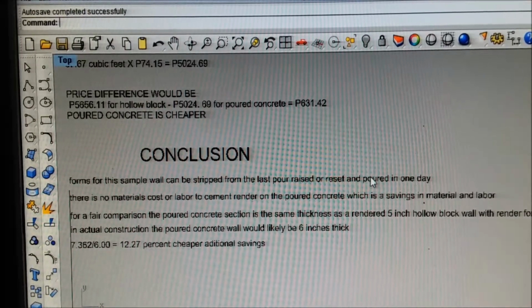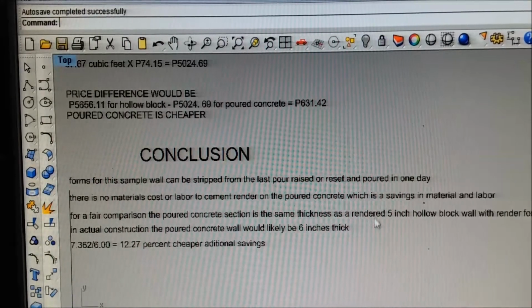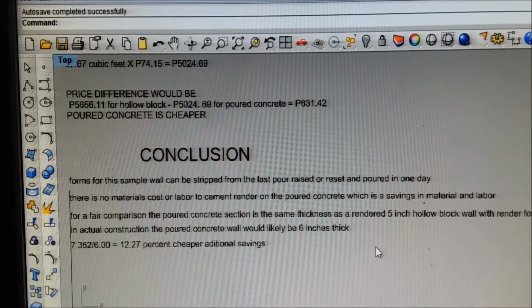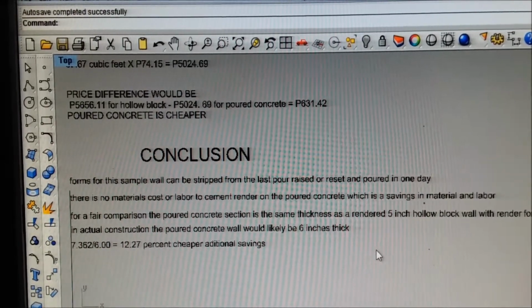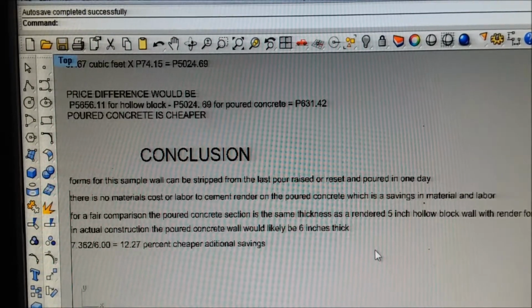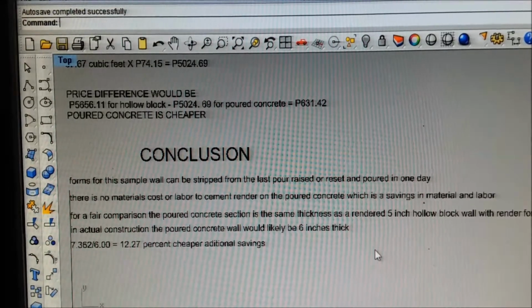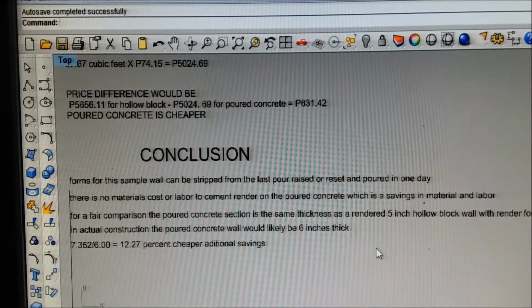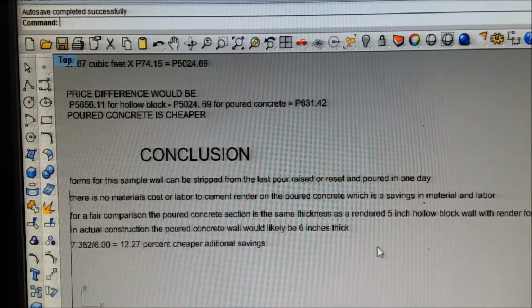For our next pours, we're going to use slip forms because I watched Texas Filipino. That's where I decided I was changing, when I saw how easy it was. But he's pouring 4 feet depth, which lets you use a thinner form. Best I can tell from his video, because he hasn't really said, it looks to me like 1/2 inch phenolic board. We've always used 3/4. It's dead flat when you use it. His walls look flat, but I was just a little leery of thinning them down by that much. So we went with a 3/4, but you really can use 1/2 inch.